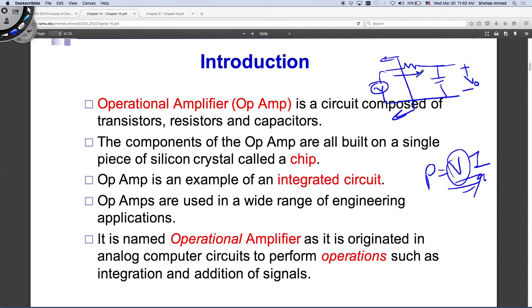So the circuits that we had before, these passive circuits, they require your sensor here. If this was your sensor, or the source is the sensor, this sensor has to have sufficient current to be able to supply your passive circuit, because there's a power loss associated with this. There's a current that needs to go through this capacitor to charge it to a certain level, right? Your sensor should be capable of doing that.